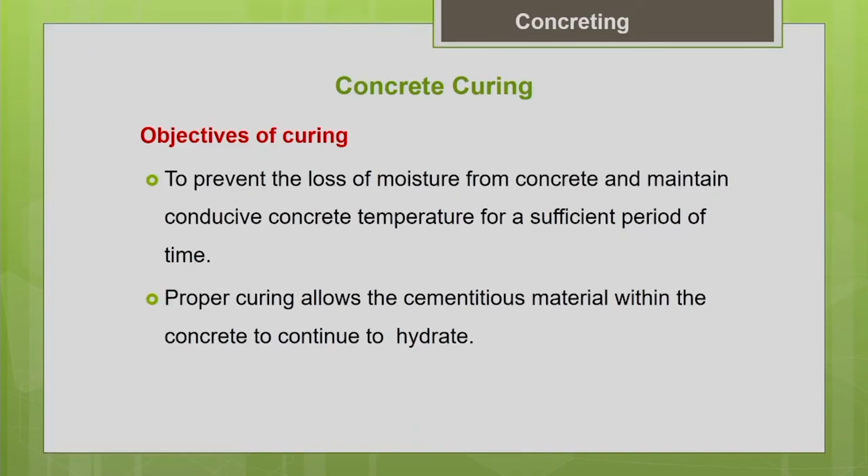The main purpose of curing is to prevent the loss of water, so that the water is available for hydration, and to supplement the water lost. Whatever the concrete has lost to the environment, we have to supplement by curing. So that is why we do curing. Curing is nothing but supplying water to concrete.